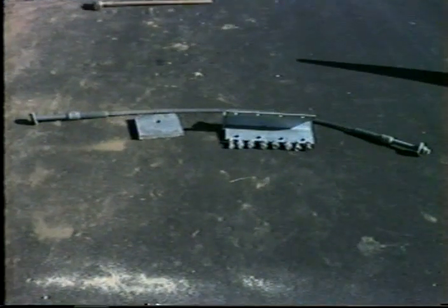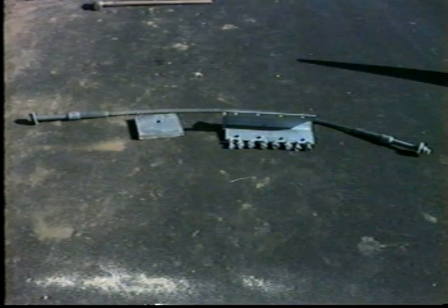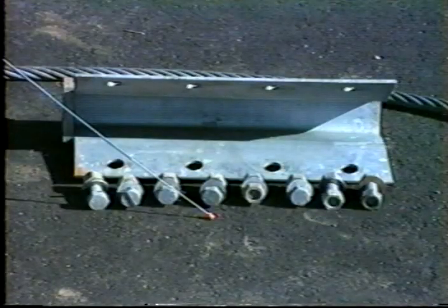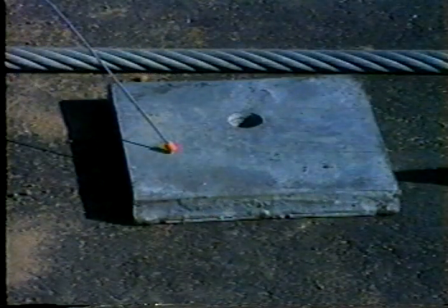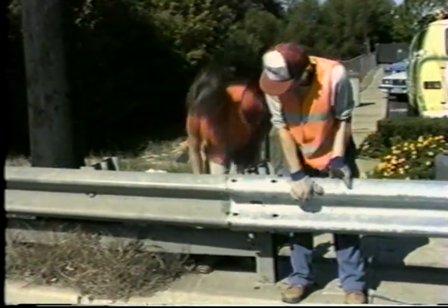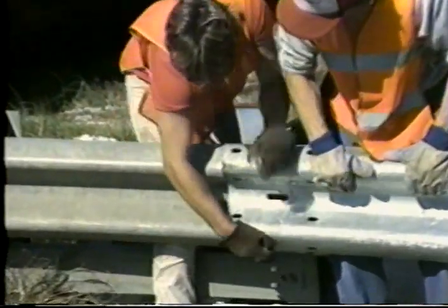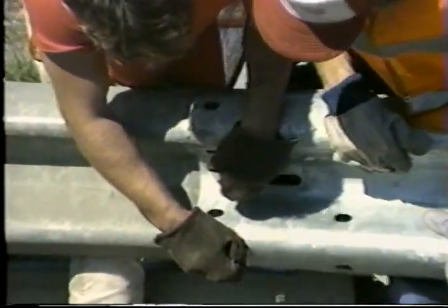Connection hardware for the BCT system simply cannot be changed from what is required by specifications. If even minor changes in bolt size or strength are made, the system will normally fail to function as designed. 8 bolts must be used to connect the cable block to the rail. Cable anchorage at the first post must be accompanied by a 3/8-inch plate. Beam splices must be lapped in the downstream direction to avoid snagging an impacting car. All bolts must be the proper size and must be tight.